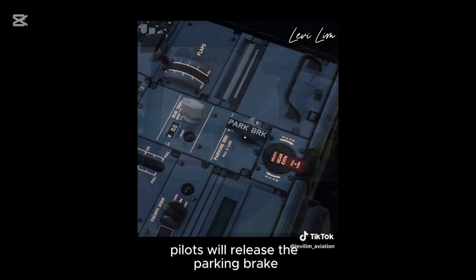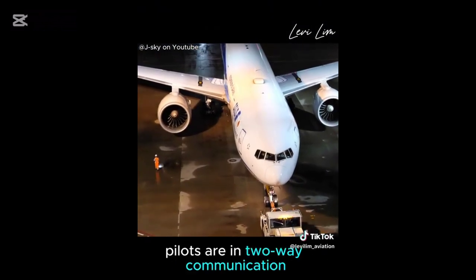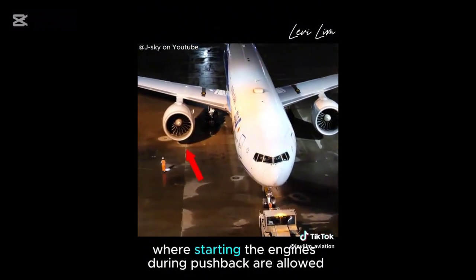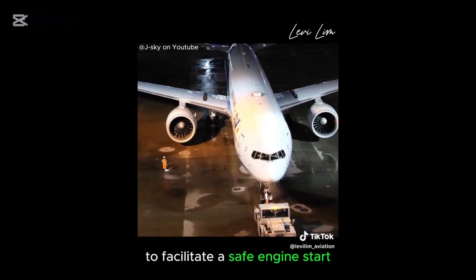Pilots will release the parking brake and turn on the anti-collision beacon. During the pushback process, pilots are in two-way communication with the ramp agents. In some airports where starting the engines during pushback is allowed, pilots will be in contact with the ground crews to facilitate a safe engine start.